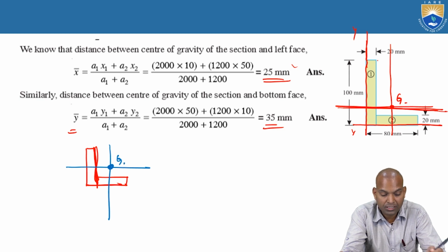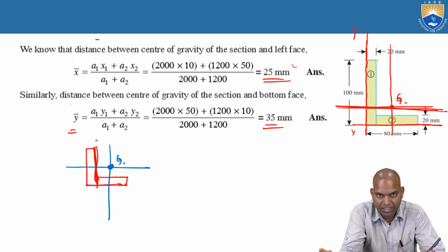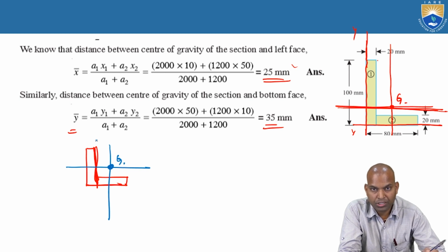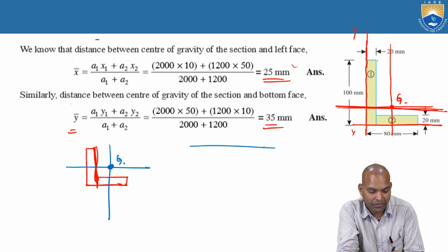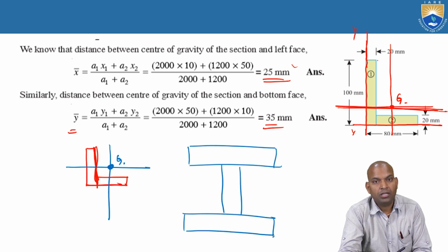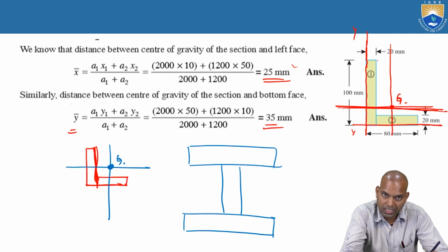Okay. There is a meaning here. Generally we have a conception that the centroid should be on the body. But we have the way of visual inspection and all. The centroid is outside the geometry for this L section. And the location of the centroid can be on the geometry when, anybody? When it is symmetrical about either a single line of symmetry or two lines of symmetry, then the point of centroid will be on the geometry of the plane.